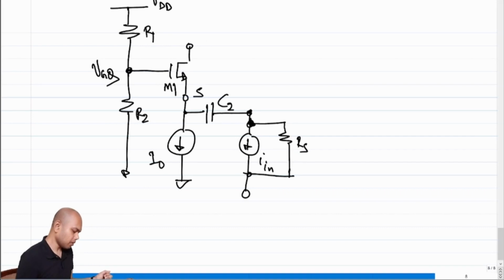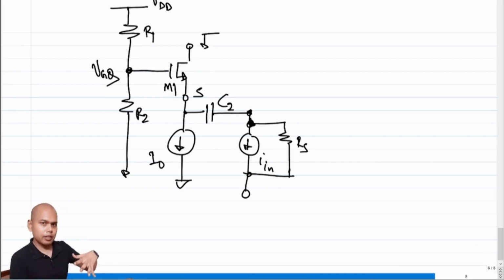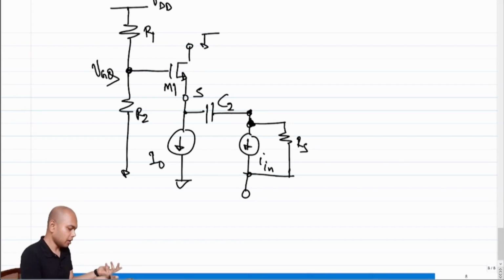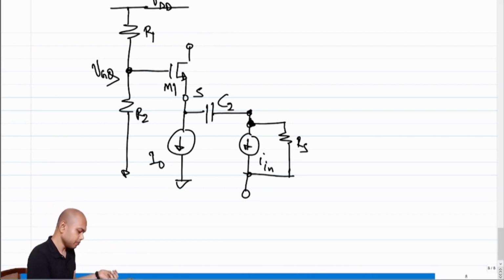What about now the drain terminal? So clearly the drain terminal impedance incrementally is infinite. Y22 is equal to 0, or gds equal to 0, which means I can take the output from the drain terminal. So in other words, the load has to be connected to the drain terminal. And how do I connect the load? I mean, I can directly connect the load to VDD.